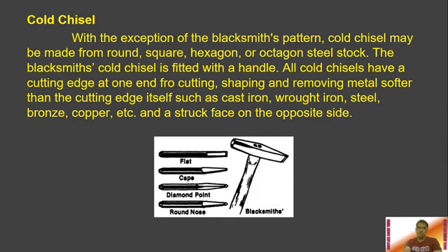Usually a cold chisel is used to chip some concrete on our wall, especially if we are going to embed our conduit.